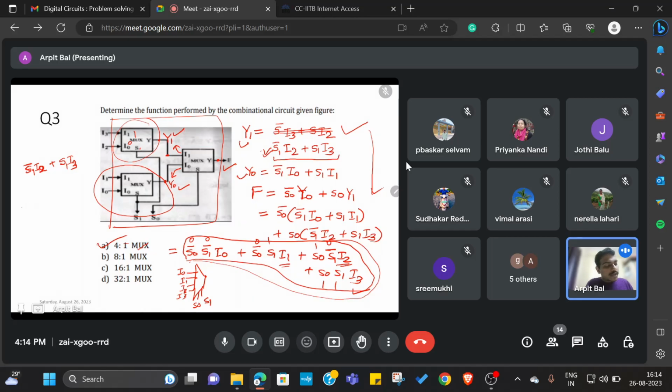But let us say you are given a combination circuit. Let's say you have an AND gate, you have a mux, then you have another mux which is connected in this way, and then there is stuff and stuff. How will you solve such a complicated circuit? You first figure out the intermediate node equations, then gradually from those intermediate node equations you arrive at the output, just like we did in this case. This is actually a very good practice that you can develop, and it will help you in the future when you try to solve bigger and more complicated circuits using multiplexers.